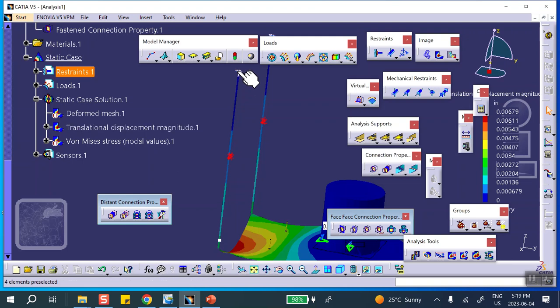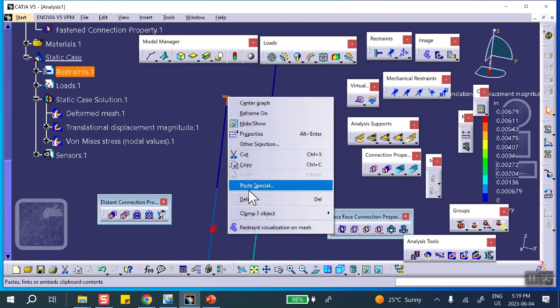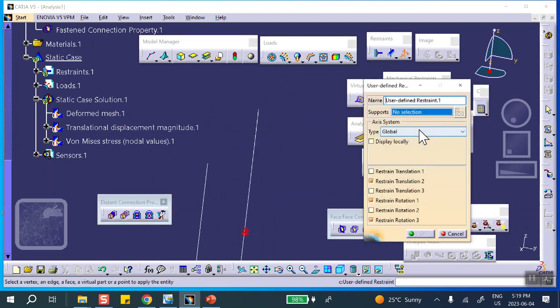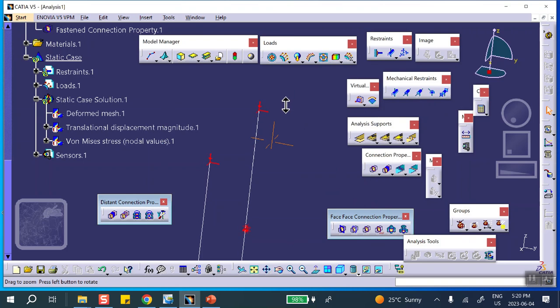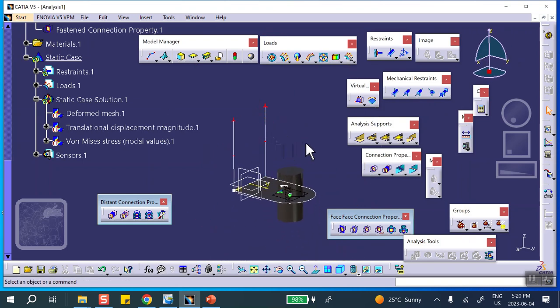So in reality, what you should do there is go there, and instead of clamp, let me take this thing away. And put the user-defined restraint with 3 translations and spinning about Z fixed. This is really a cable up there, because the way we did it, that point on the top was also clamped in terms of rotation, but now we remove that.